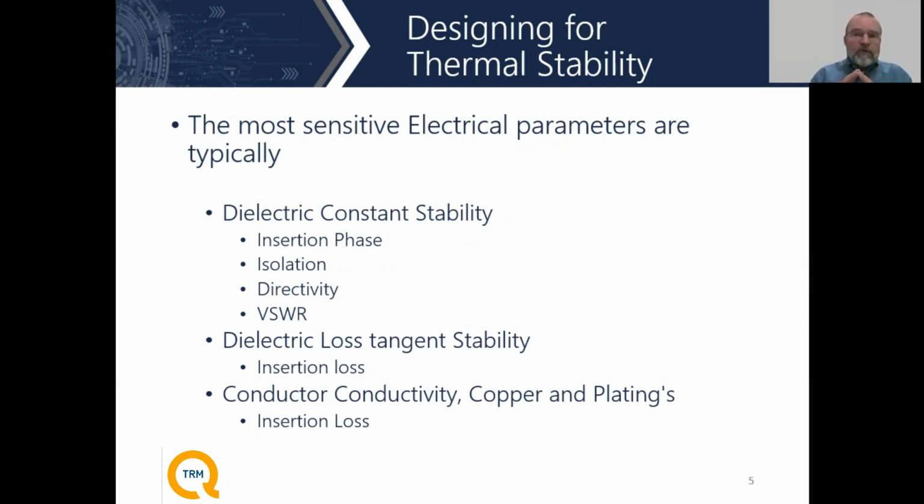Teflon is something that is widely used in the industry, and it varies significantly over temperature as far as its dielectric constant is concerned. These sorts of changes can change insertion phase on units fairly dramatically, just due to the propagation speed difference from the changing dielectric constants. It can have a big impact on insertion phase. Other parameters,